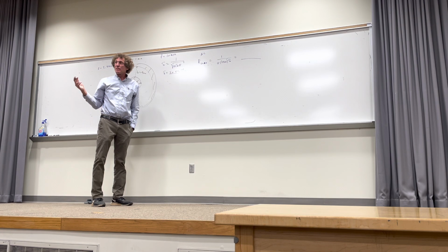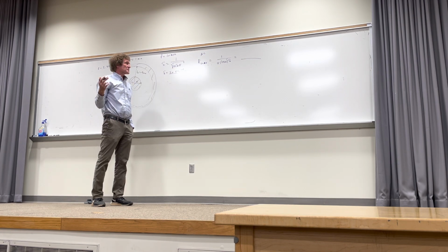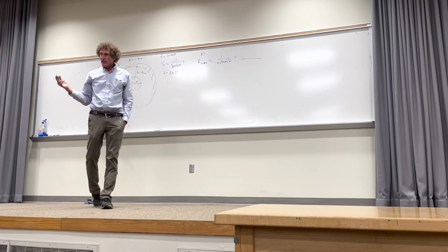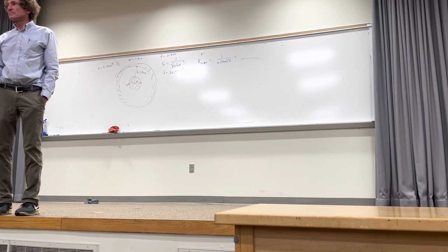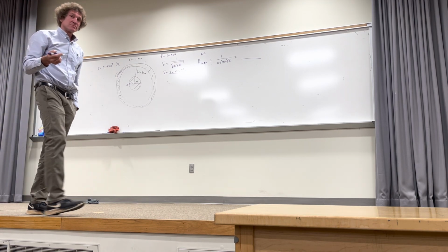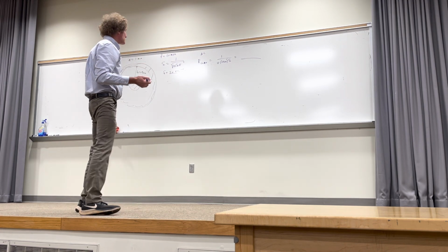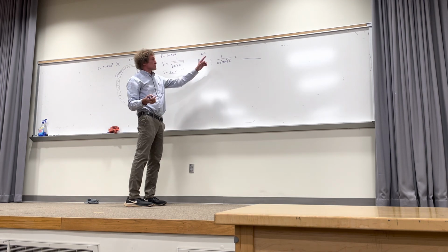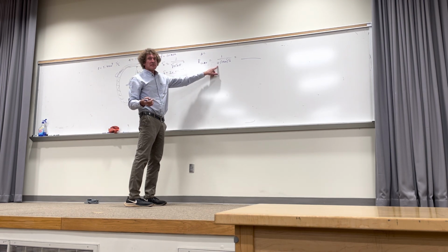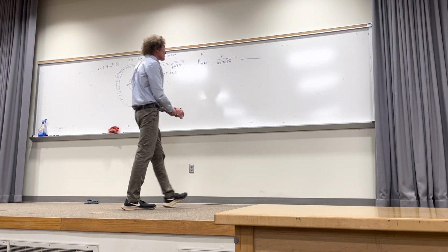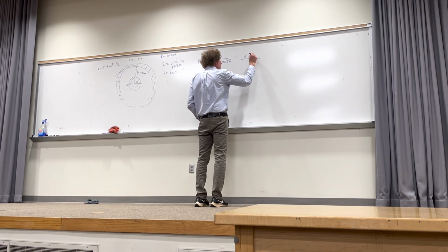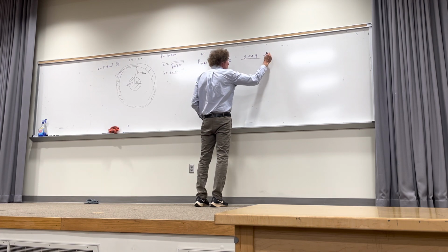I'm not sure if the core is that. Overall, I think you'd given the overall. All right, well, let's just get for the core first. This is just the inner conductor. One over 2 pi A times skin depth times sigma. 0.949, and would that be ohms per meter?